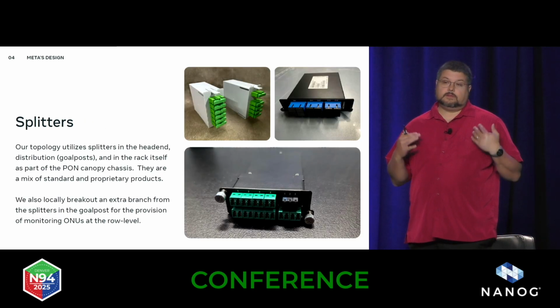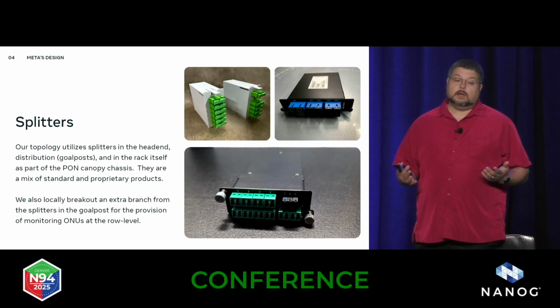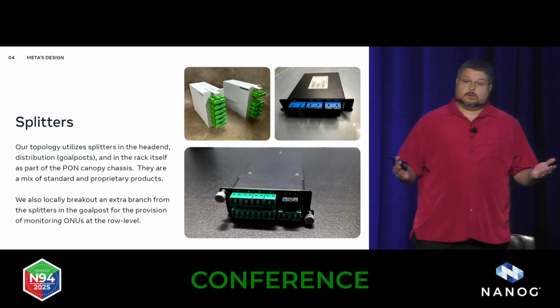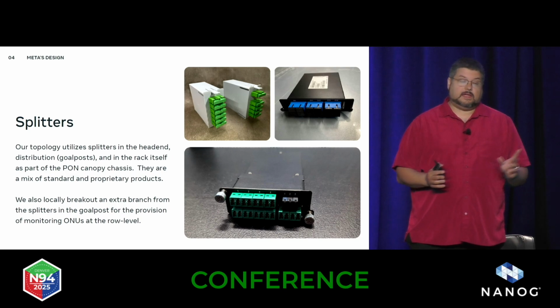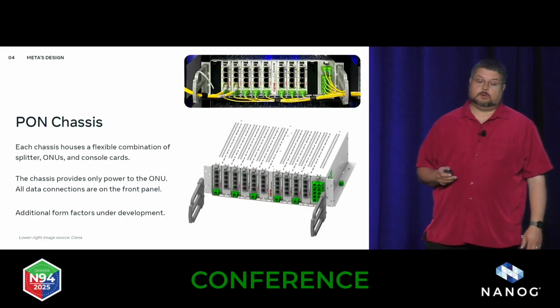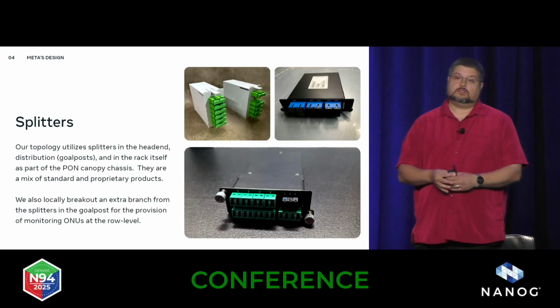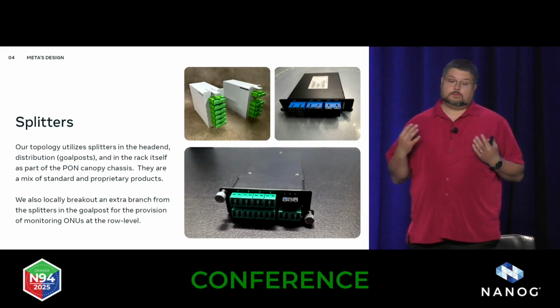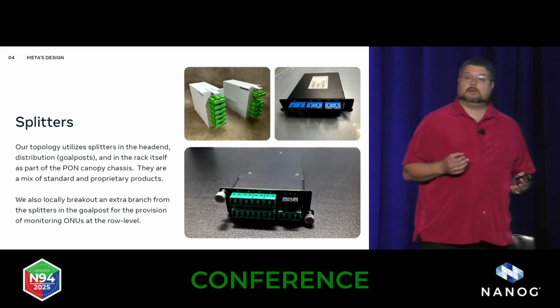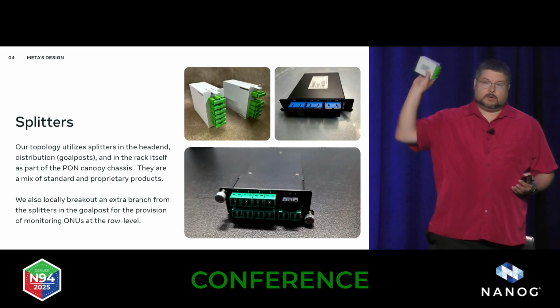We also have the ODN. That's the optical distribution network. I mentioned that's also passive, and that has fiber as well as splitters. Now at the end of that canopy, you probably saw there's a bunch of fibers going into another module. That's a splitter. That device has no power. It's just basically a physical enclosure that fits in the canopy that has either 1 or 3 splitters in our design. Here's an example of one here.